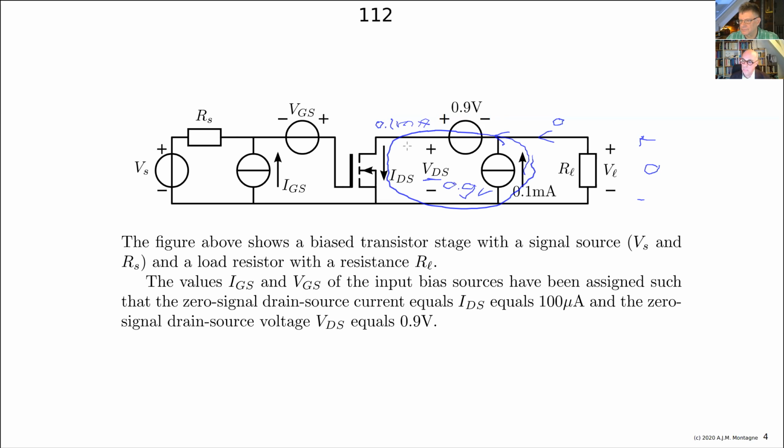So this is just again the same. You take the product of the branch voltage and the branch current. If it is positive, there is dissipation. If it is zero, there's nothing: no energy delivery, no power delivery, and no dissipation. And if it is negative, then the source is delivering power. For the current source, it is zero because the voltage across it is zero. And for the voltage source, it is negative because the current flows through the minus to the plus terminal through the device. So the product of branch current and branch voltage is negative. Yes, I hope it is clear.